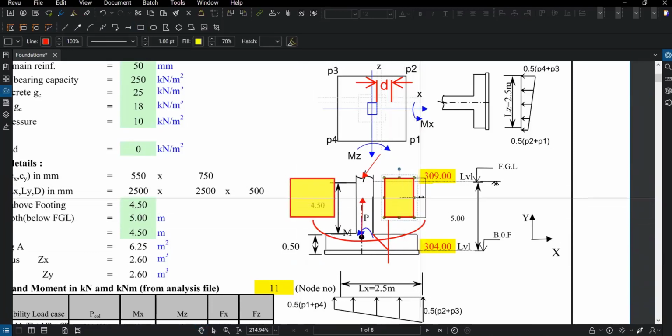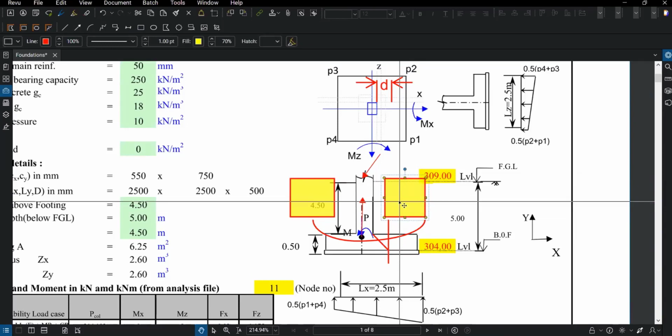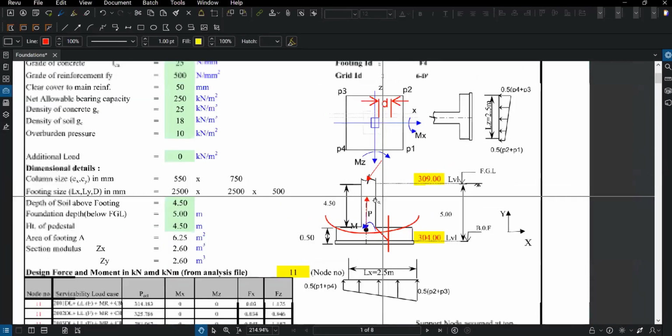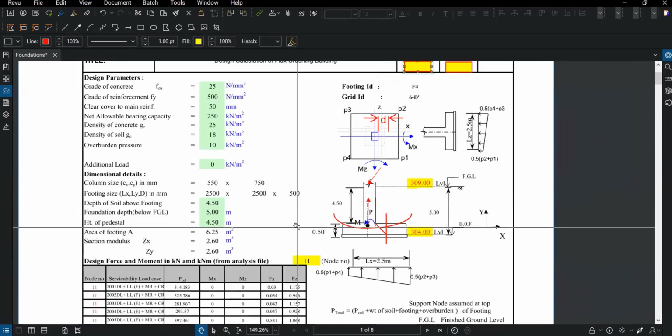Whatever is here. So what do we have here? We have soil, we have submerged condition water, and we have some surcharge. For that, the plate bends in the other direction. And for that bending moment, one needs to provide a rebar on the top of the foundation as well. Otherwise, there isn't much requirement of providing the top rebar, but one can provide the top reinforcement for general crack width requirement as well. And that concludes the explanation of the case study.